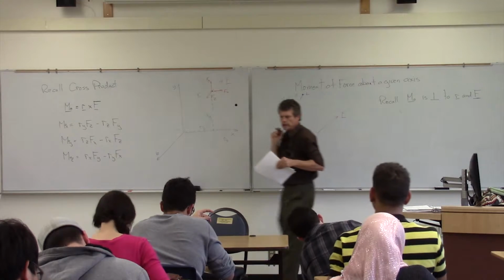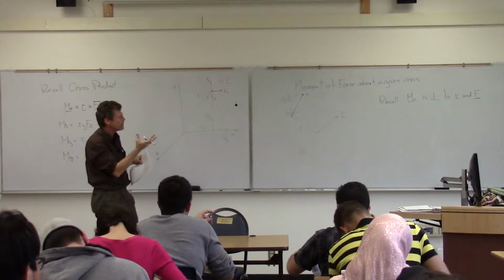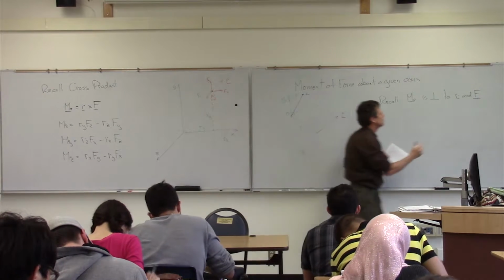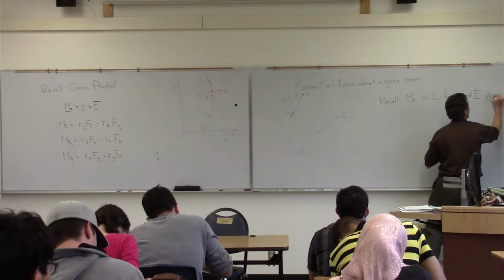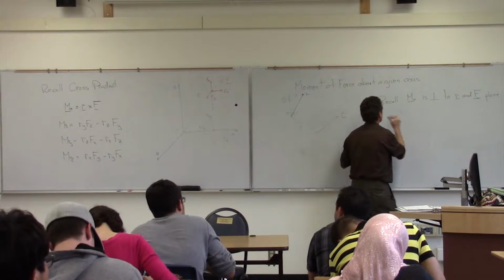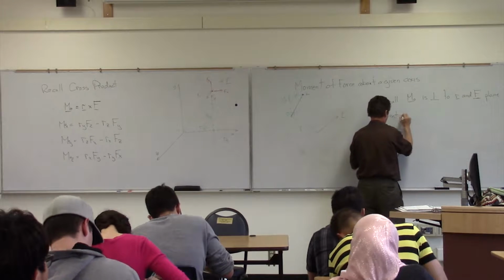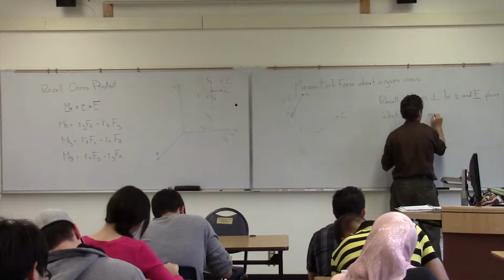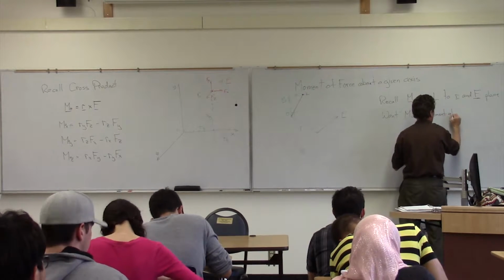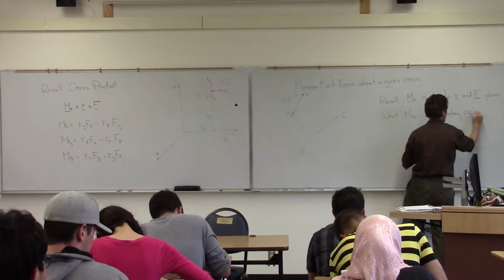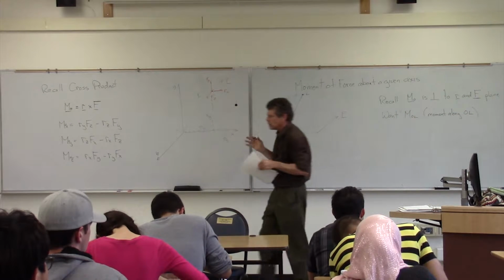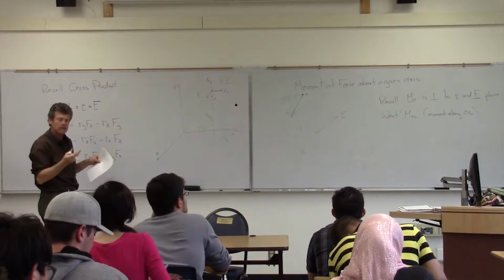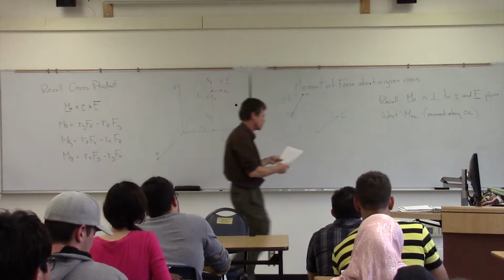Okay, that's my perpendicular sign there again, shorthand there. So M naught is going to be perpendicular to this plane created by R and F. But again, as a designer, we're probably interested in looking at specific pieces. So what does that force create in terms of there? I might need to design my weld to resist that force.